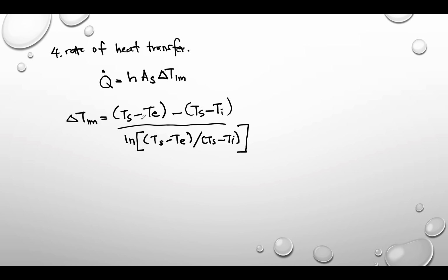But we do not have the value of Te. Previously, we assumed the arithmetic mean of your flow, but it doesn't mean that we have to substitute the assumed value into this equation. Since we want to find whether we assumed the correct exit temperature, we have to find the T exit of your flow.